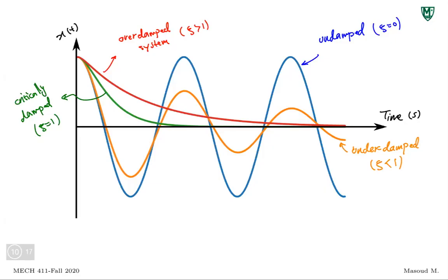What if C becomes smaller than C critical? Then suddenly you're going to go from a critically damped system that comes back to its position without oscillating to an underdamped system, which is oscillating. And that's what you don't want. You don't want a bathroom door that goes back and forth. That's actually dangerous. So in most designs, we always tend to do an overdamped system design to make sure that even if things change a little bit, it is still doing what we want. No oscillation.